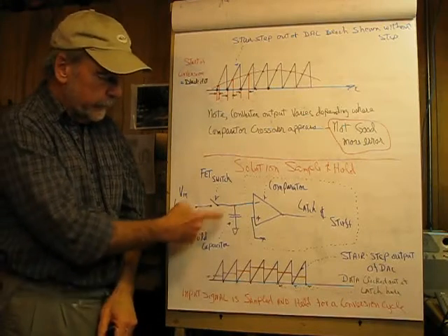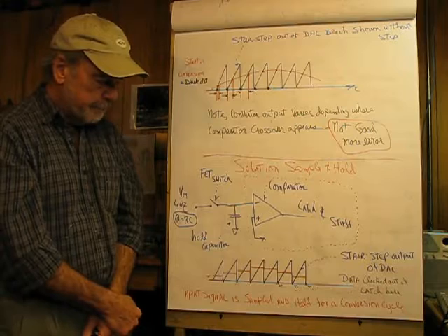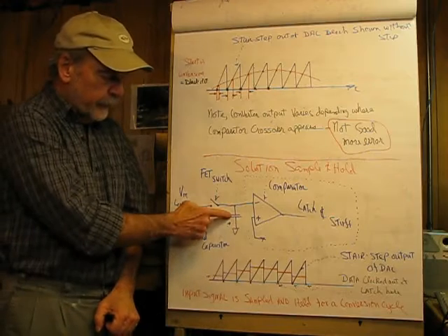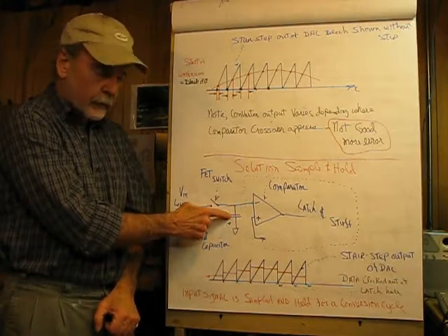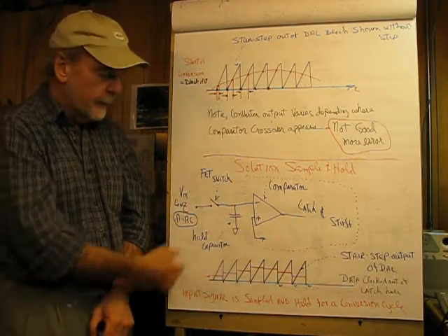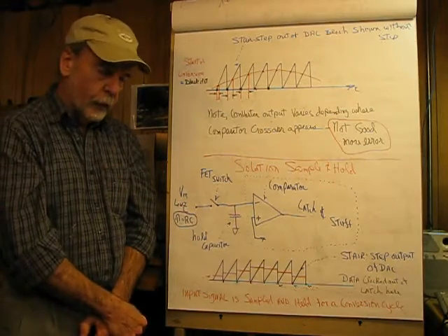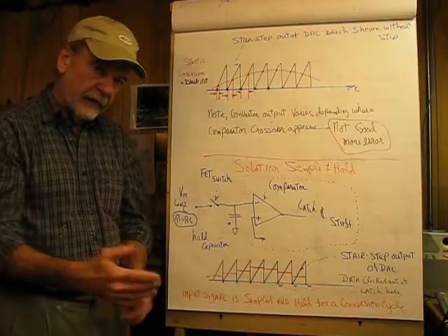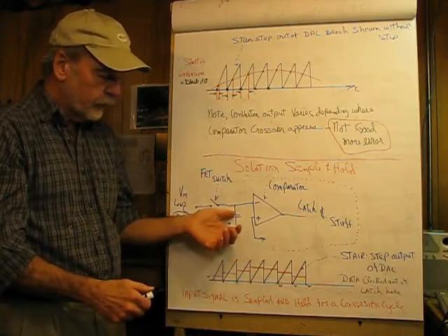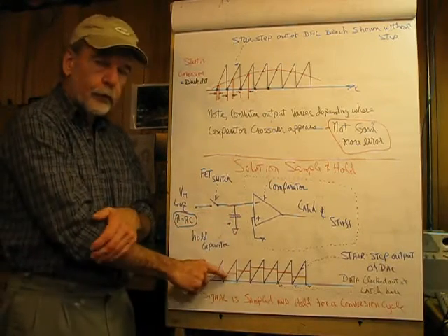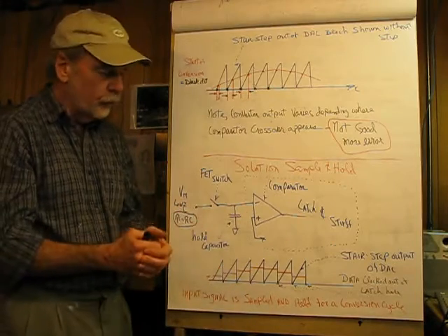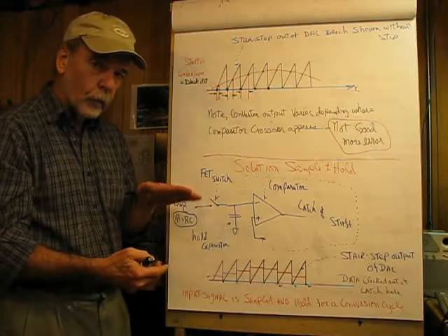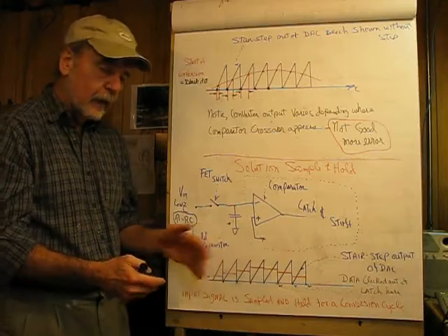Now, capacitors leak. Time constant tau equals R times C, so when we do a sample on this, we've got to pay attention to how large this capacitor is and what the impedance of the driving source is. FET switches like a CD4016, not that we'd want to use that, have certain channel resistances and so forth that have to be taken into effect. Further, since capacitors leak, the actual voltage would droop a bit. So droop is a term used in the language of sample and hold to indicate that it's not a perfect hold, and that will add to the error in the output.